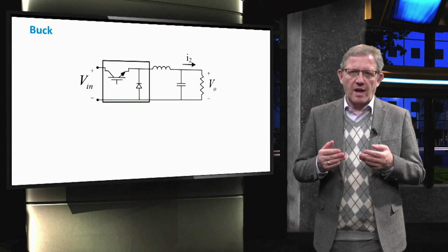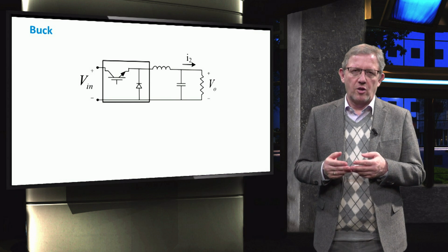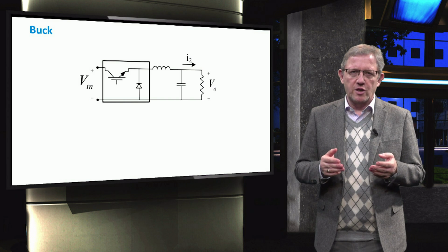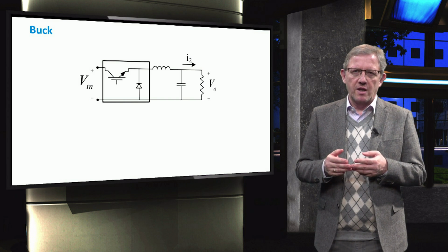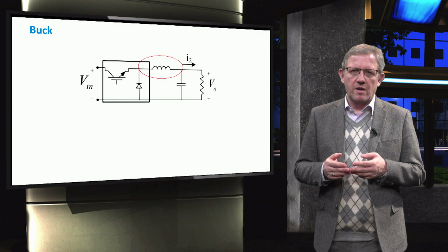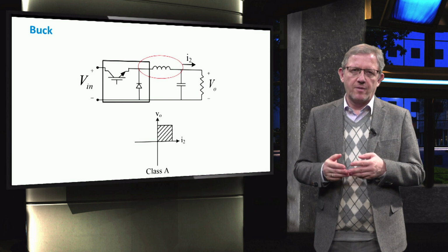We determine the class for the configuration of a conventional buck converter. Note that since the input voltage of a buck converter is greater than the output voltage, the current of the inductor will not obtain negative values. Therefore, buck converters are considered as a Class A.